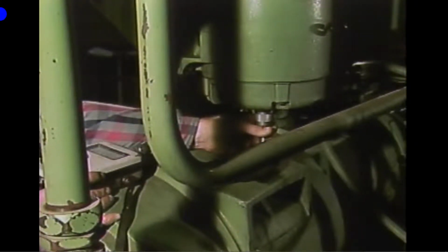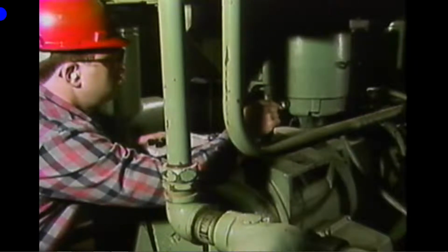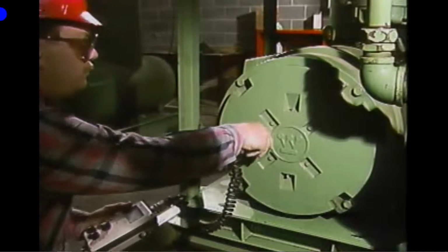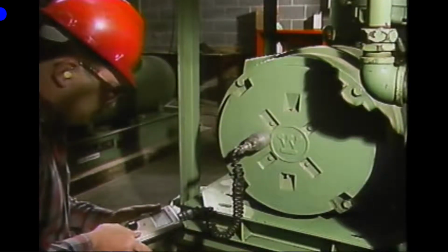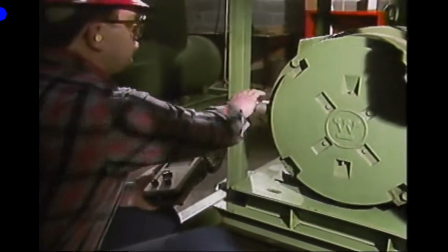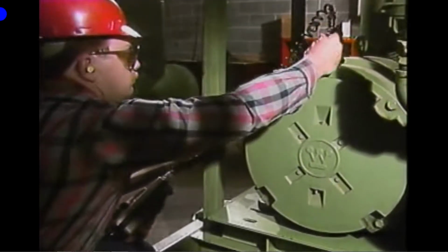That's the minimum number of directions needed to completely check the vibration. For example, the bearings on this vertical shaft should be checked from an axial direction, that is, parallel to the center line of the shaft, from a radial direction, that is, perpendicular to the center line, and from the second radial direction, that is at a 90-degree angle to the first radial measurement. On a machine with a horizontal shaft, the bearings would also be checked from an axial direction and from 2 radial directions. Typically, one radial measurement is taken horizontally and the other is taken vertically.